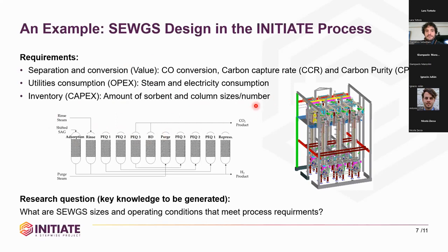And to give a bit more context to this, you see here, for those who don't know, a pressure swing adsorption system is essentially operated batch-wise in different stages. So we first operate as a water gas shift reaction absorbing the CO2, and later on we have multiple steps where the pressure is changed to regenerate and extract the CO2, and then go back to the higher pressure and get ready to produce hydrogen again. And this is done in multiple columns, so that we can always have continuous hydrogen and CO2 production.